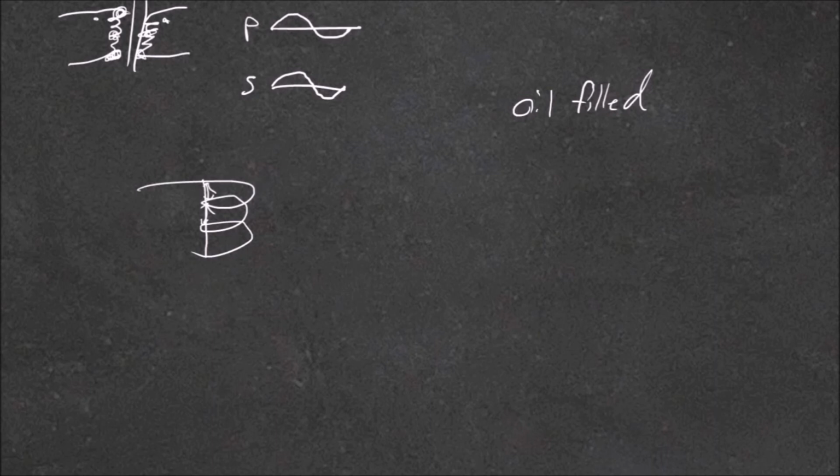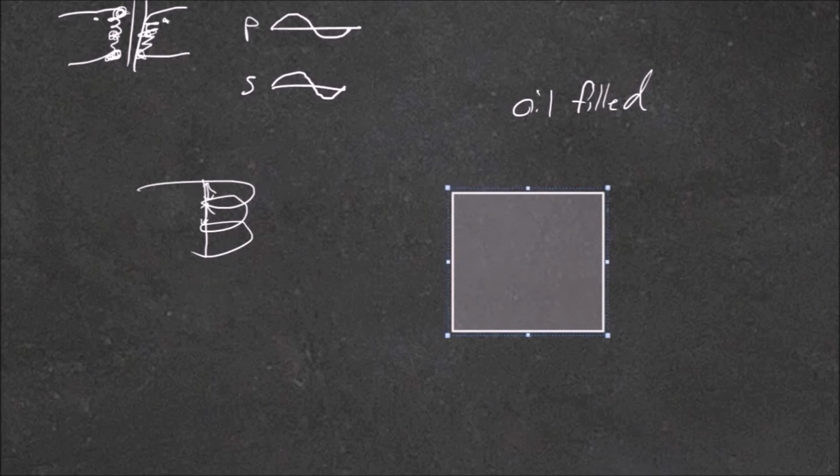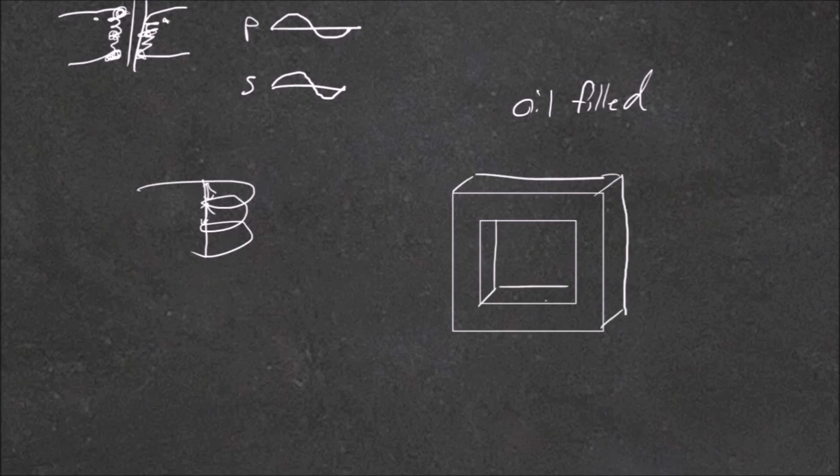And finally, the iron core of the transformer wouldn't be one big chunk of iron. The transformer is made of thin sheets which are laminated together, but insulated from each other. So you've got heaps of sheets of iron stuck together. And this reduces something known as eddy currents.